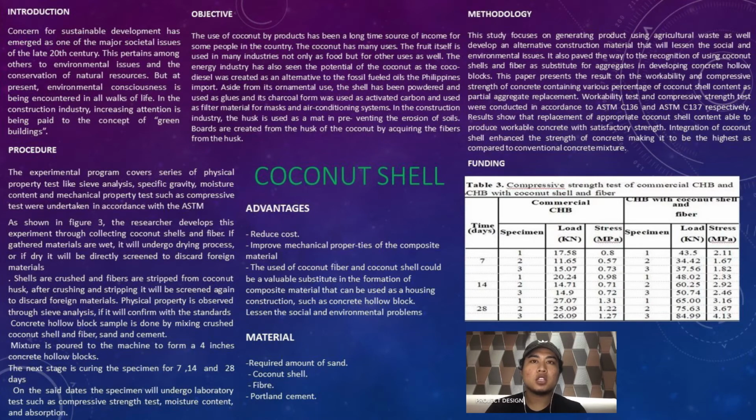Second is mixing. The concrete is then mixed for 6 or 8 minutes. Next, once the load of concrete is truly mixed, it is dumped into an inclined bucket conveyor and transported to an elevator hopper. So the next step is molding.